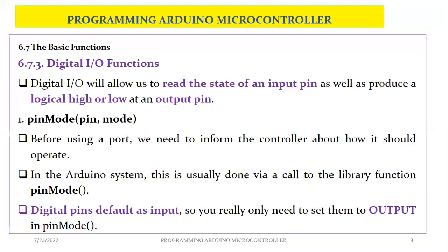concerning programming Arduino microcontroller. In this video, we are going to look at the application of digital input-output functions to the programming of Arduino microcontroller. The digital input-output functions serve two main purposes in Arduino microcontroller environment. The first function that we can put the digital input-output functions to is to help us read the state of an input pin.